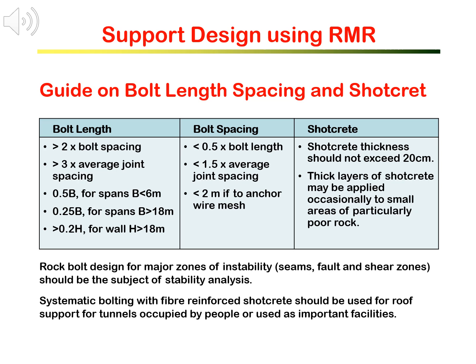The maximum bolt spacing is recommended to be 0.5 times the bolt length or 1.5 times the average spacing of joints in the rocks. If wire mesh is to be anchored by the bolts, then a bolt spacing greater than 2 meters makes attachment of the mesh practically impossible.